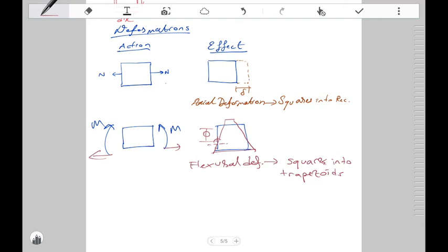We say that axial force causes axial deformations, moment causes curvature. That's the way we relate the internal forces and the corresponding deformations. We have one more deformation type, but I will not focus on torsion here.